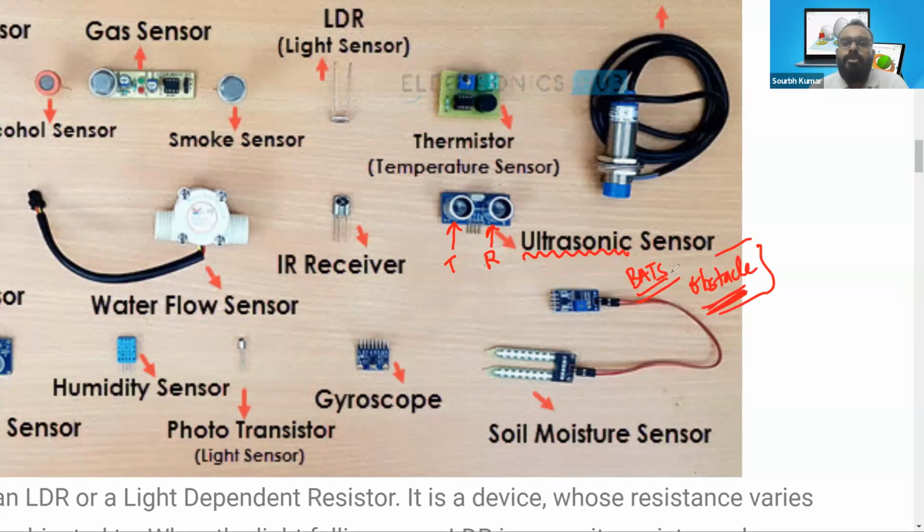Through the same concept, engineers built this device to produce ultrasonic frequency from the transmitter. When the transmitter transmits the ultrasonic frequency, it travels on for some distance. Then, upon reflection from the obstacle in front of it, it bounces back and the receiver end receives the same.